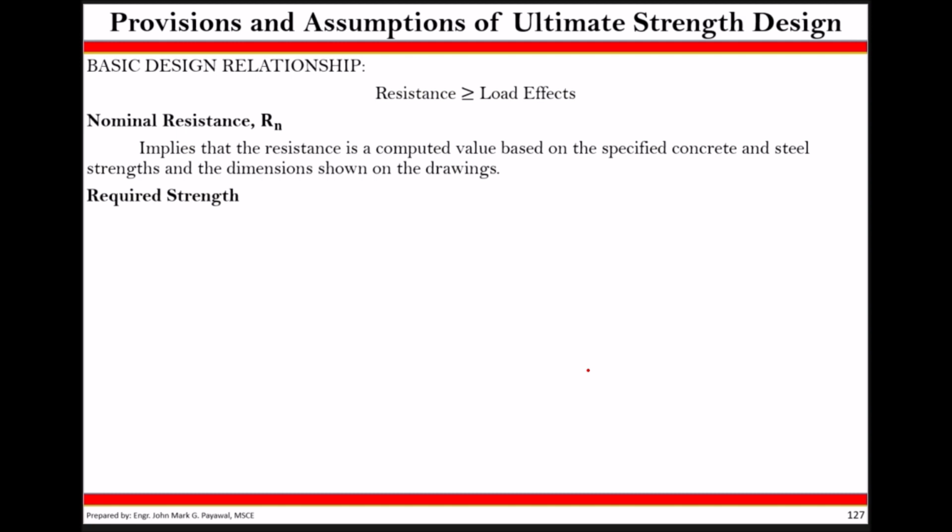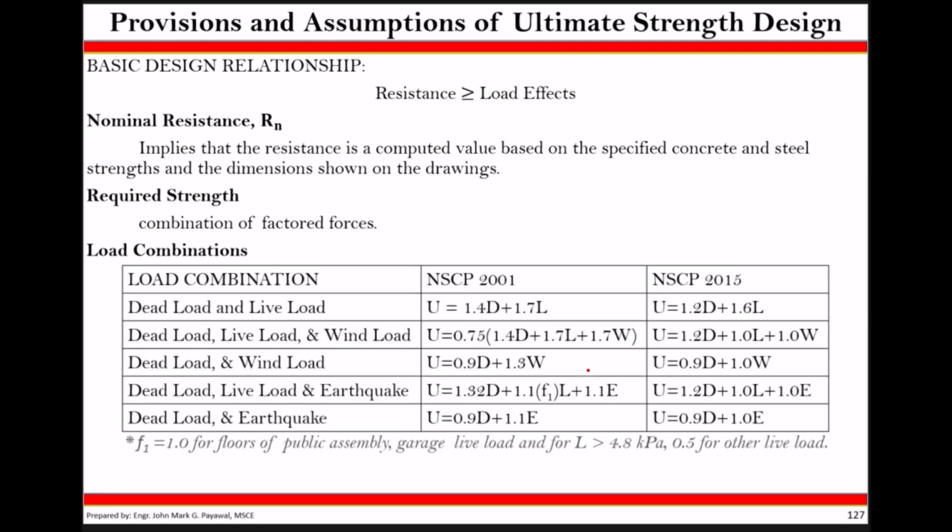Consequently, you have your required strength. Ano naman yung required strength natin? This is taken from the combination of your factored forces. Here, we have your load combinations taken from the NSCP 2001 and NSCP 2015.